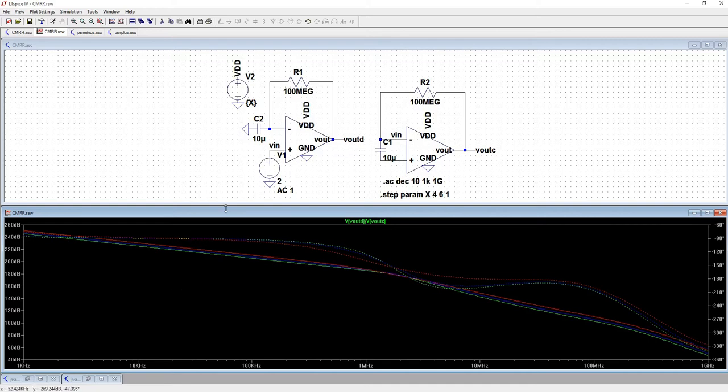And we saw that because if there was any sort of offset between V plus and V minus with that bias of 2.5 V, when VDD is 5 volts, we would see that DC voltage amplified through to the output, which we didn't. That's how you can understand that if you have an input signal and your output signal isn't a perfect amplification of that input signal, you don't have very good common mode rejection ratio.